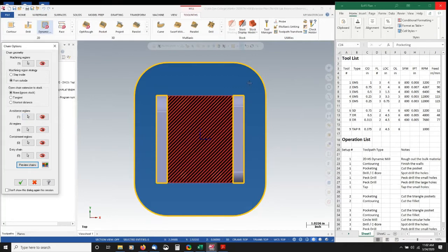And you have walls that are preventing your tool from moving too far past your machining region. Now this blue area is the area that you're deciding is safe for your tool to enter. So it can plunge in the blue area without any risk of plunging into material.